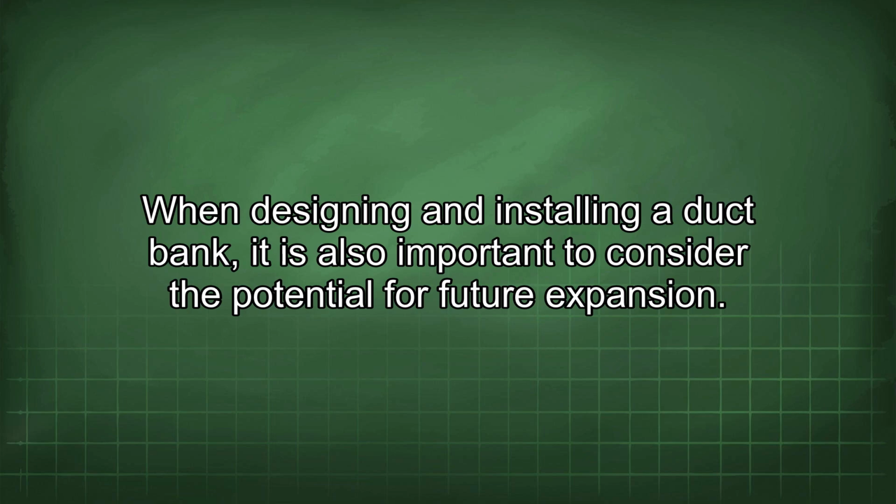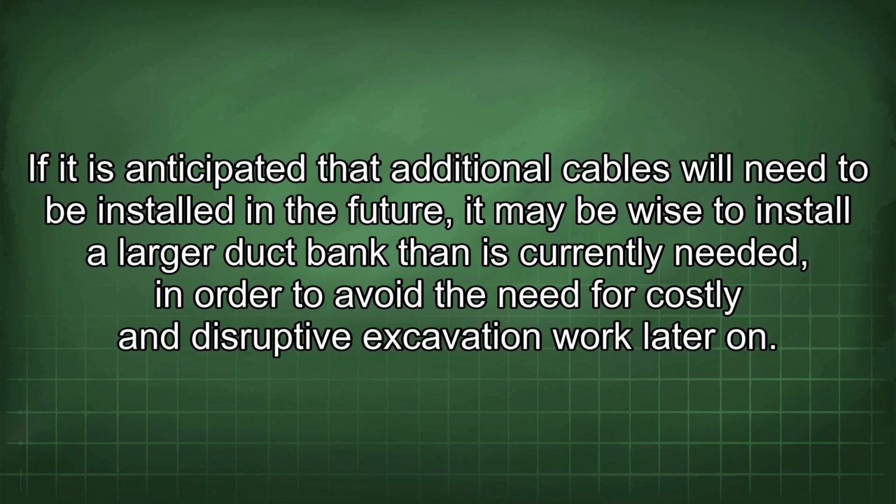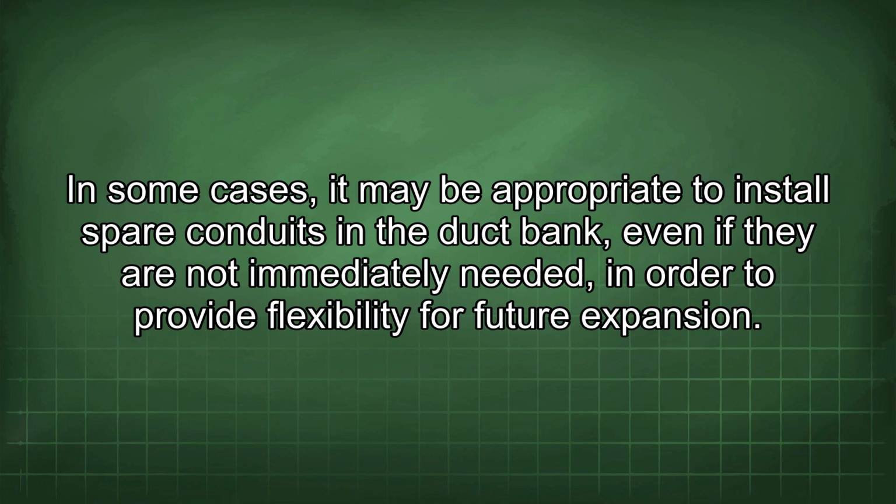When designing and installing a duct bank, it is also important to consider the potential for future expansion. If it is anticipated that additional cables will need to be installed in the future, it may be wise to install a larger duct bank than is currently needed in order to avoid the need for costly and disruptive excavation work later on. In some cases, it may be appropriate to install spare conduits in the duct bank even if they are not immediately needed, in order to provide flexibility for future expansion.